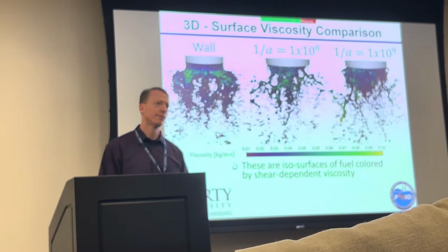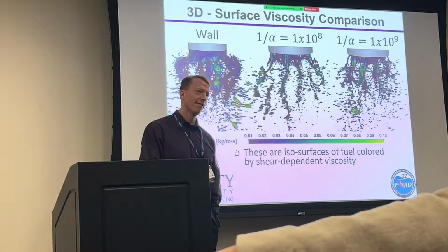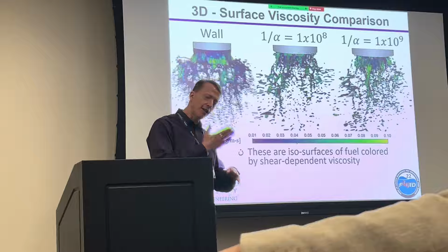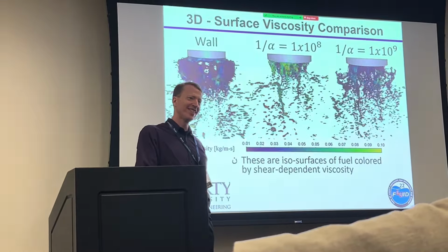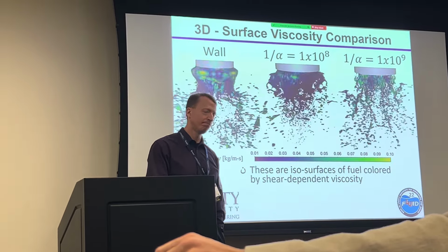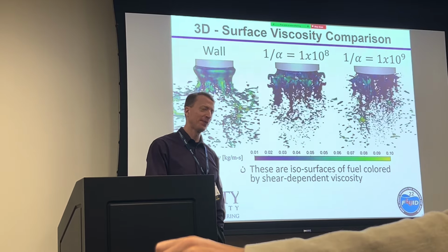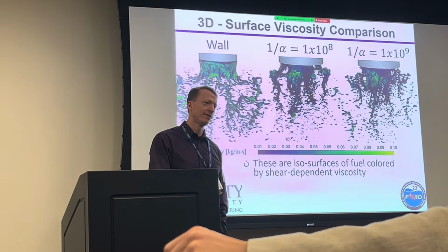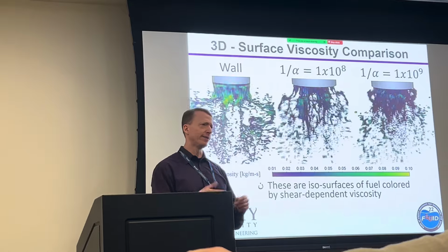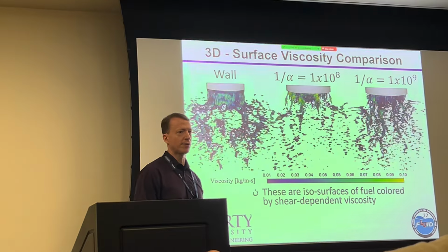Because we were also doing a similar case, and I'm normally using octree because then you can reduce the cell count. I don't like to cut cells of octree, but I know. Yeah, me neither. But we figured out that for these VOF to DPM cases, octree shouldn't be used because it just cuts, and the liquid doesn't spread like normal. Do you have a similar experience or not? Yeah, I do. Octree is kind of like ANSYS automatic mesh refinement. And that's a problem for PLIC, for the piecewise linear reconstruction.